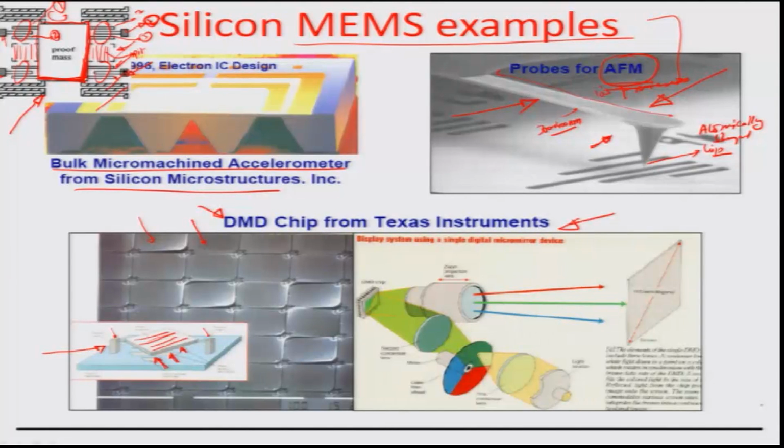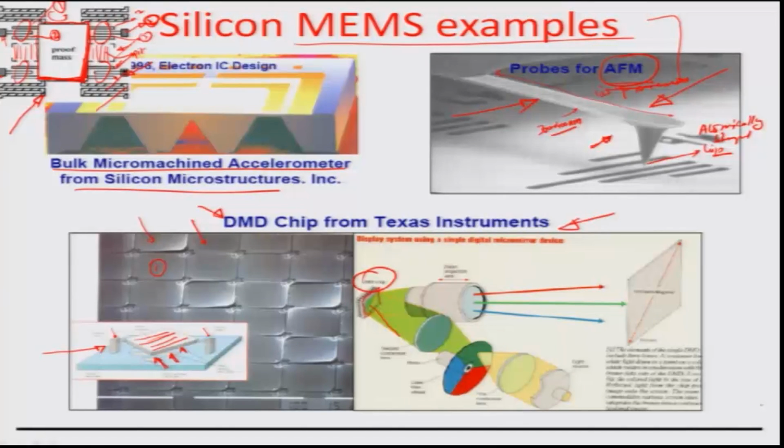The idea is that if there is a light beam falling on this DMD chip, you can see right here that it passes through the RGB filter, for example, and formulates an image on this particular DMD chip, and let us say there is a beam of light which gets reflected off such a plate. So, let us say this plate 1 is reflecting a beam of light. By twisting and turning the plate around its hinged axis, there is a possibility of either focusing a ray to the focus of the aperture lens, the magnifying lens, which finally magnifies the image onto the screen. Or in other words, it can be deflected so much that the beam goes out of focus, and so it is no longer there in the aperture of the projection.